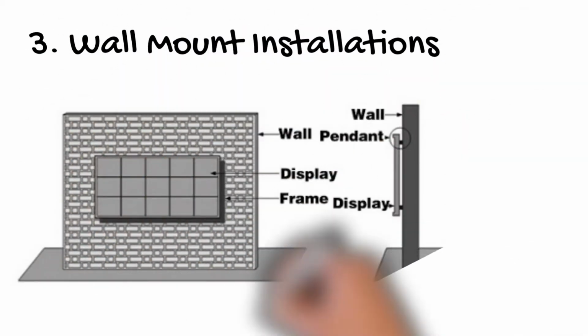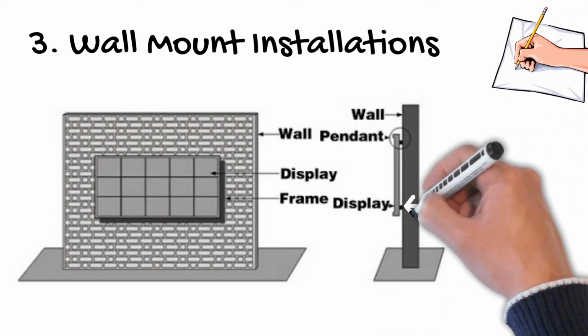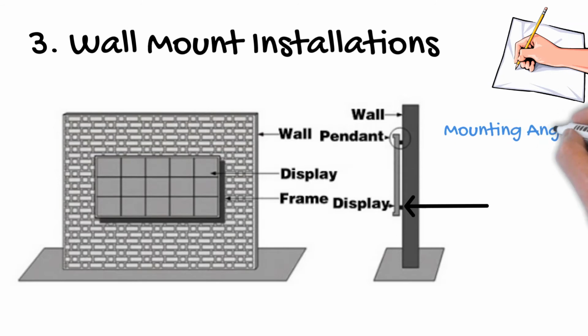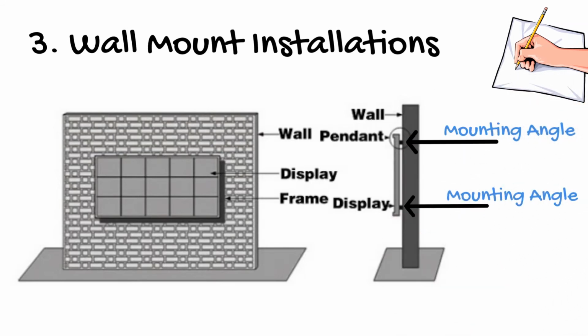Number 3, wall mounts. Most signs can be fitted with wall gussets or angles at the back of the sign to mount to nearly any surface. For engineered drawings to be produced, you will often need to provide specifications or even elevation drawings for the existing wall to be sure the installation is planned correctly up front. The main variable is the amount of attachment points that will be required to meet the requirements of local code and safeguard the integrity of the wall being used.